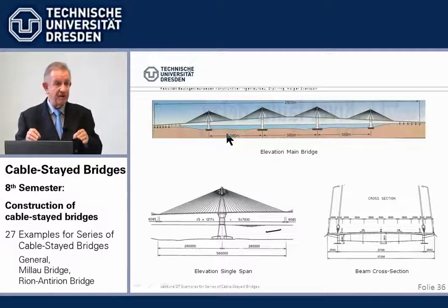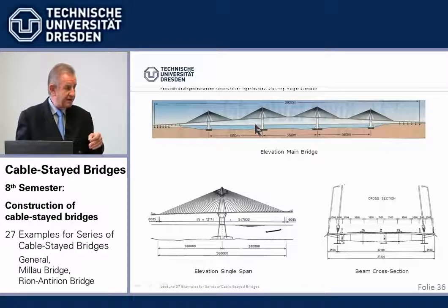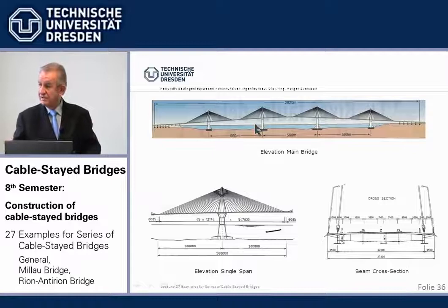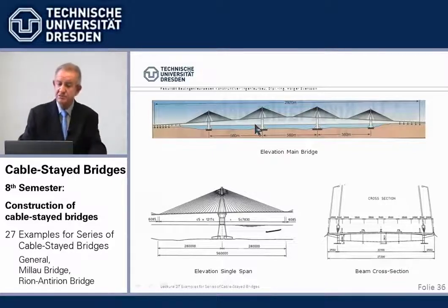Mio, they were very high. Okay, cost money. But with sliding forms or jumping forms, it's not so bad. But here, we had to make them fit against the earthquake, which made them per unit even more expensive in relation. And the more expensive the piers become, the more overall economic it is to make the spans longer. I think that's a very basic issue.